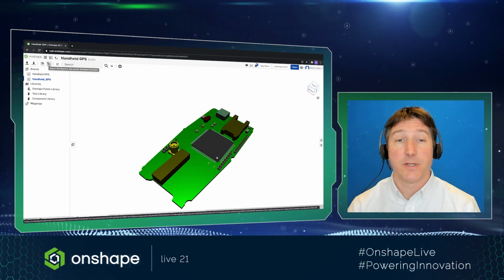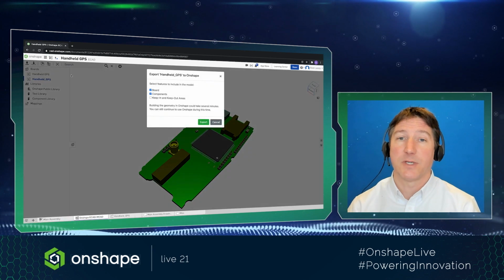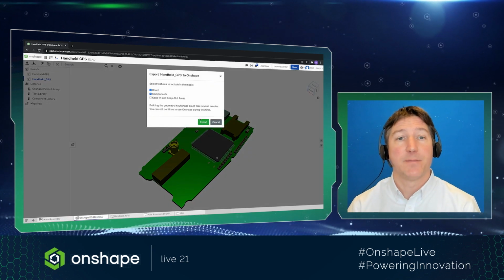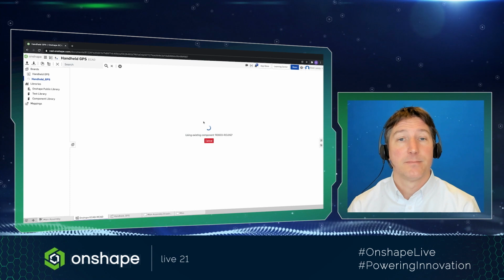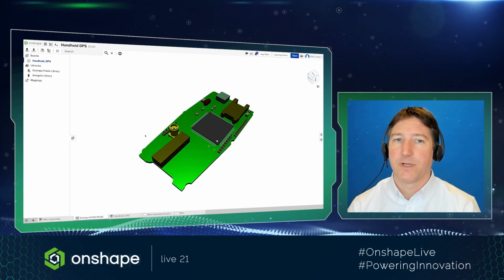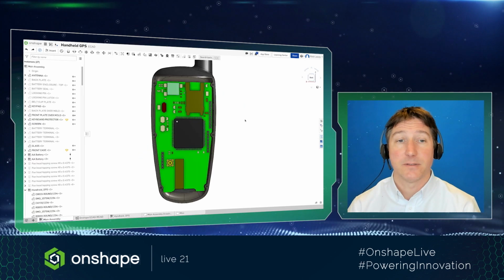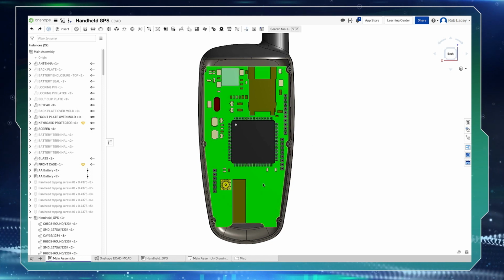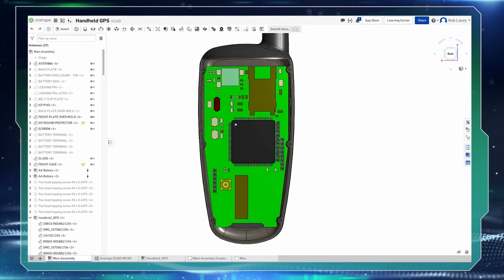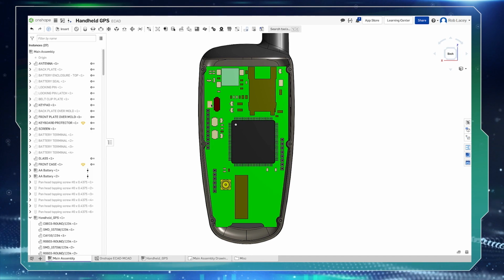At this stage, this is still only a preview, however. It doesn't exist as an Onshape assembly yet. So the next step is to build the board and components in Onshape. Onshape will automatically create new models for any new components that have been defined in the ECAD data. With our Onshape assembly created, we can see there are a couple of problems, and some components, such as these connectors and the USB holder, will need to move.